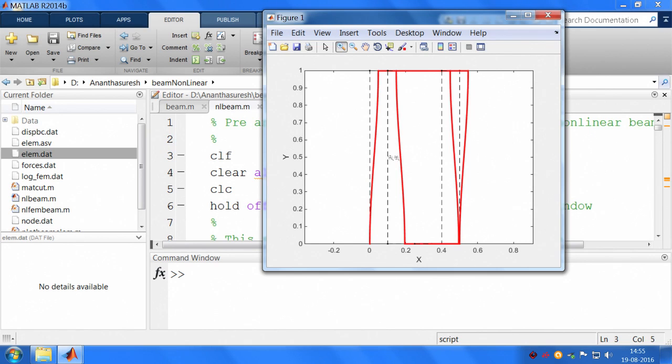From here to here for the second stage there will be a different amount of deflection. So, if you know those deflections ahead of time, you couple them using the corresponding lever ratios. There were letters A and B. If you arrange them correctly, you can make sure that even under large displacement this particular stage will not have any vertical motion. Okay. So, now we have a stage, we are applying force, it moves like this, right.